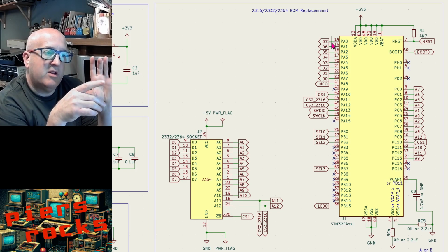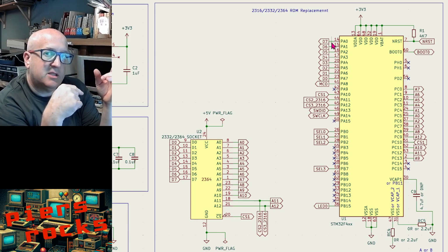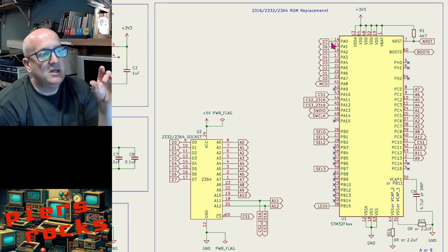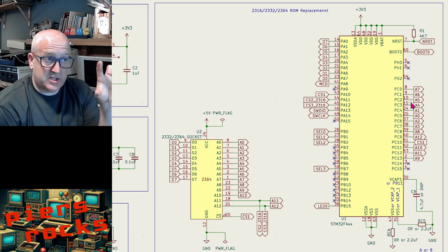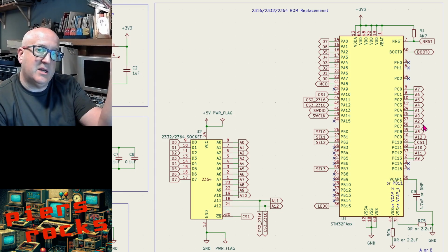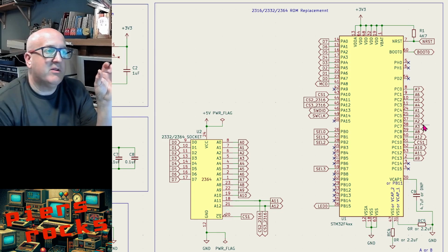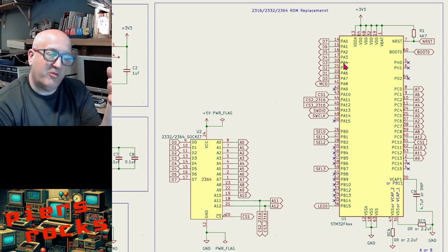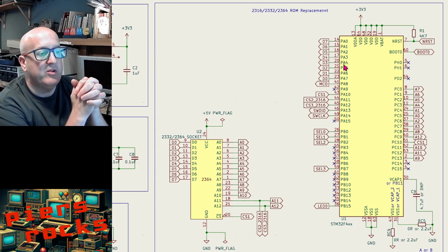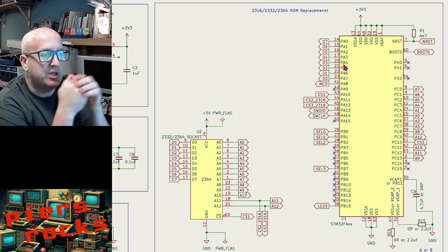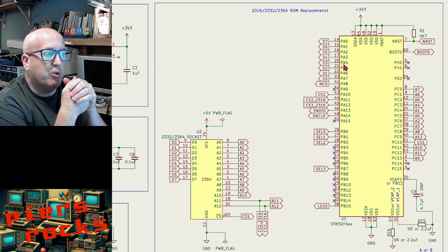And then it rearranges the addresses that the particular bytes are found at, so that the STM itself can just take this particular ordering of address pins and address the image with that. Similarly, I'm flipping the data bytes around so that they're the right way round for being written by the STM to this output port. Sort of code that takes me quite a while to get my head around and make sure that it's working properly.